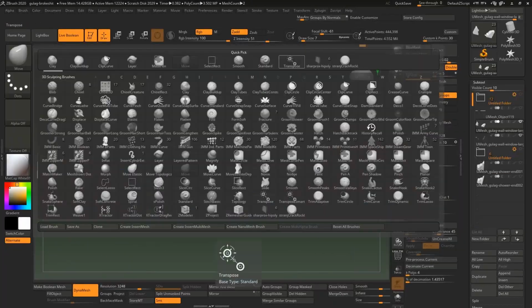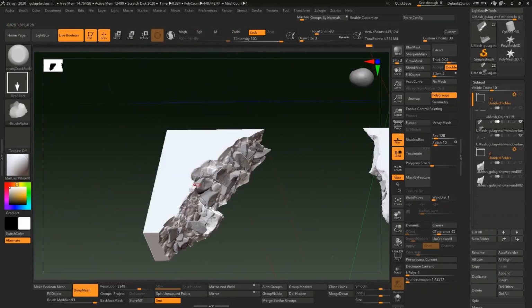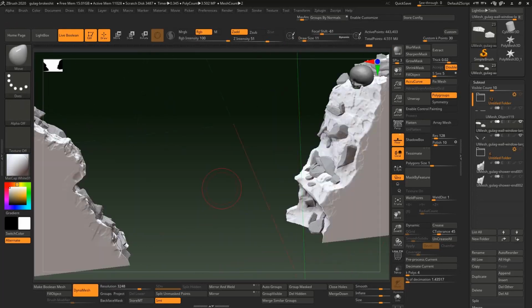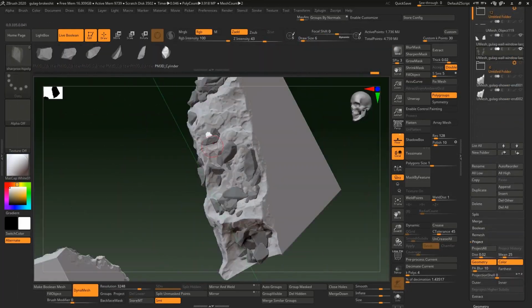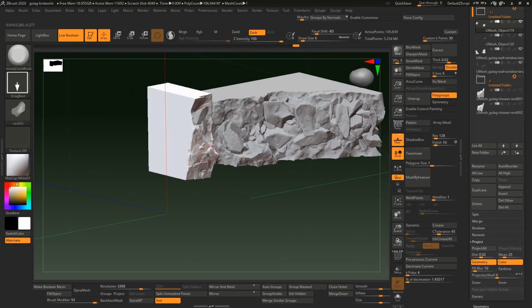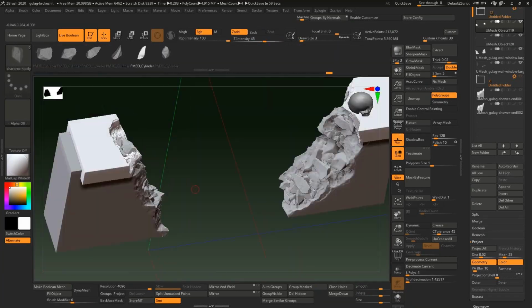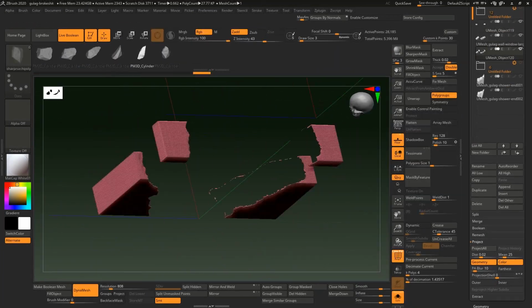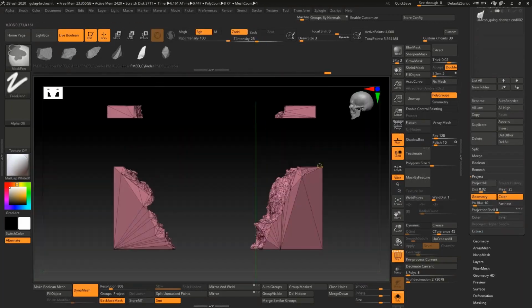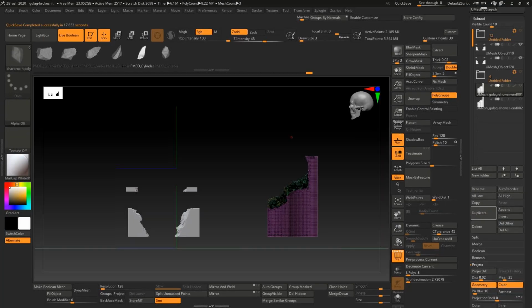So I had my high poly models of the broken edges. But the only way I was going to get those to match up perfectly with the low poly models was by hand. So I got low poly models from ZBrush, which featured the broken parts. And then I had to take them back to Max and vertex by vertex match them up with the original mesh, to cut into the original mesh in a similar way and then merge them up.